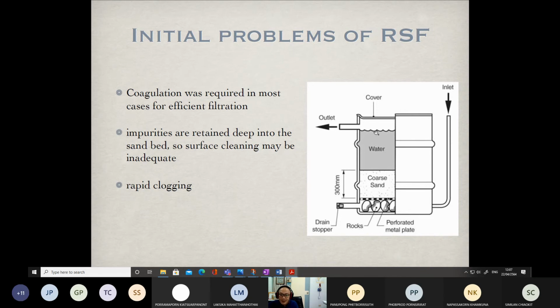So if you think like this is the tank, and if we put the media, water is supposed to move smoothly to the bottom, but there is media here. So it reduces the cross-sectional area, and it will also create the head loss. Head loss can be simply observed as the water levels shown inside these tanks.